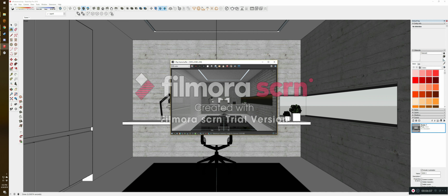So I would recommend, if you download lamps from the warehouse, to embed your cone light in them, or sphere light, or whatever kind of light you're using, because V-Ray will actually account for the geometry of the light itself. So yeah, we are nearly ready for a final render here.